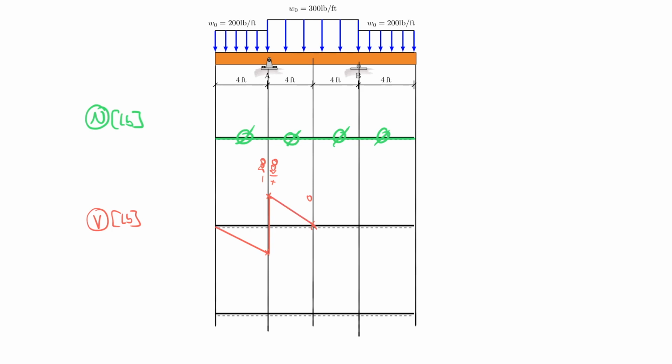And now you may ask yourself, how does the other side look like? And I let you think about this for a second while I complete this. And maybe you can go ahead and do that. I often see a common mistake in the classroom now, that the students actually think, okay, it's a symmetric system, therefore it goes up here and then goes down and then like this. But one thing we need to talk about is that if the system is symmetric, the shear force is actually anti-symmetric.